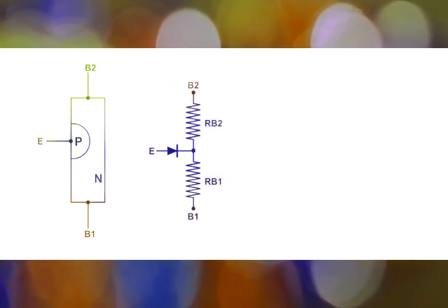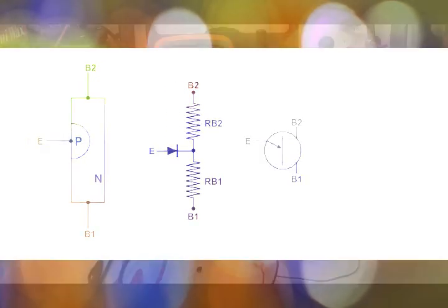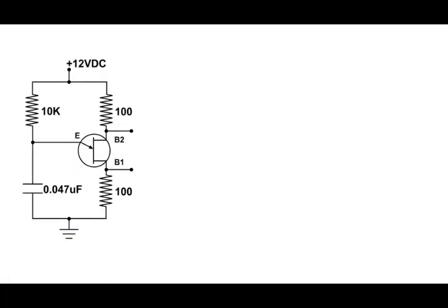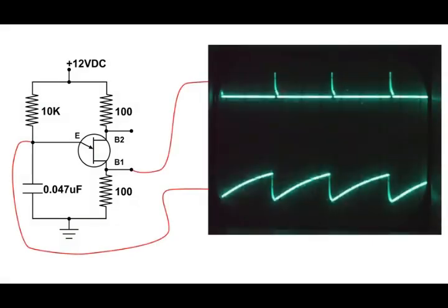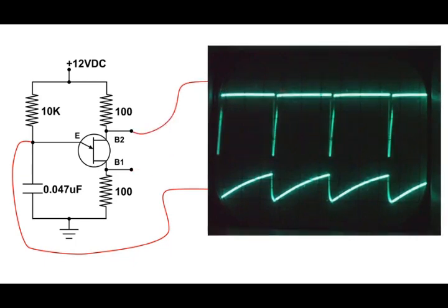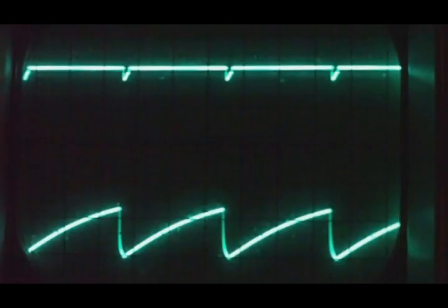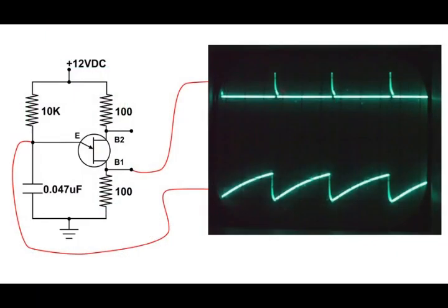Although the unijunction transistor has the name transistor, its switching characteristics are very different from those of bipolar junction transistors or field effect transistors. These transistors cannot be used for signal amplification, but instead can be used as switching transistors. UJTs have unidirectional conduction and negative impedance properties that make them act more like a variable voltage divider during breakdown.